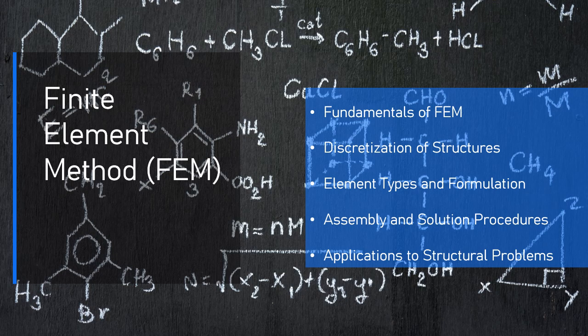4. 2D and 3D coupled elements. These elements are used for problems where multiphysics analyses are required, such as thermomechanical interactions or electromagnetic fields. These coupled elements incorporate more than one physical effect in their formulation. Examples: thermomechanical elements couple temperature and displacement fields in thermal expansion problems. Piezoelectric elements, used in analyzing structures under mechanical and electrical coupling, e.g., actuators.